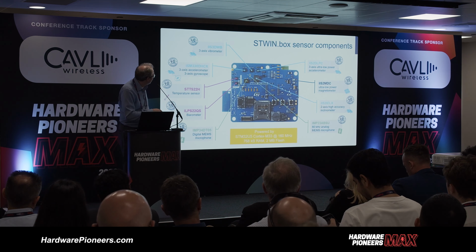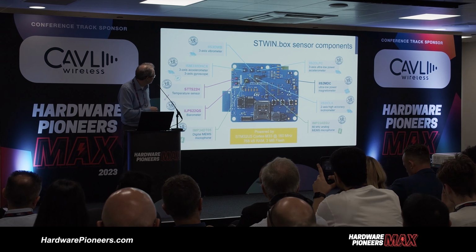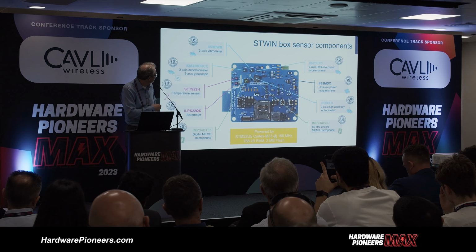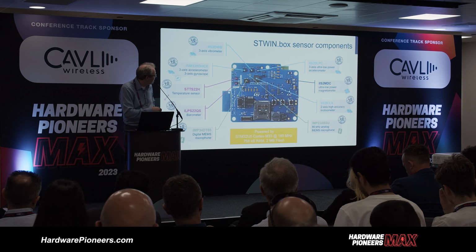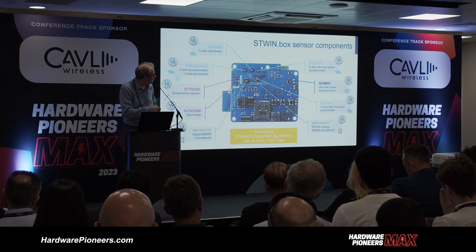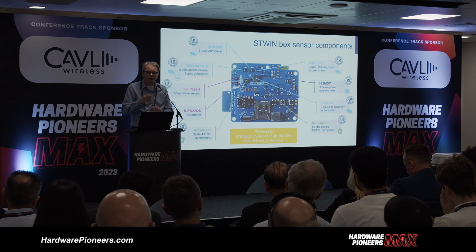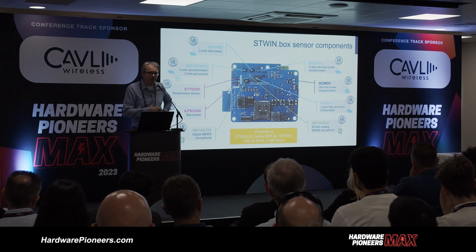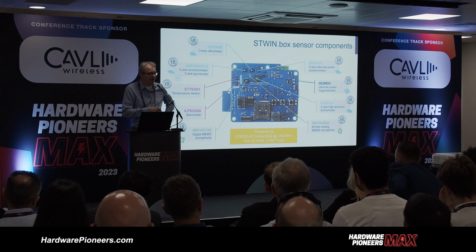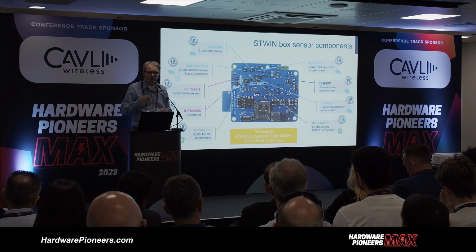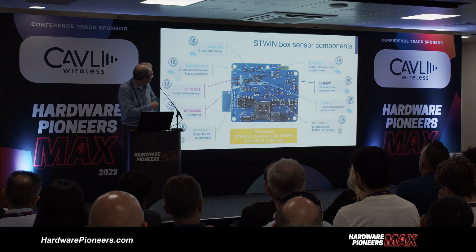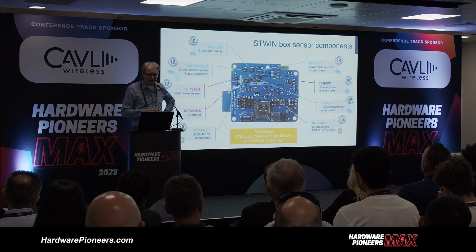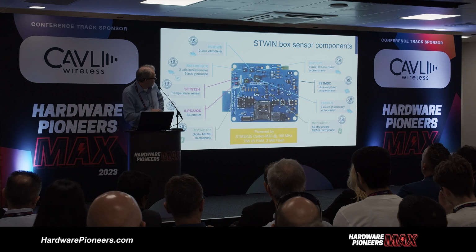We can start from here, the acceleration sensors. So to mention that we had the 6 kilohertz component. This was the 6-axis IMU, but we have also one which is a very low power component. This could be used, for example, for the initial wake up of the system, that this component takes only 0.4 microamps of current, and then it could wake up the whole system based on a small shock on your device. And it's actually being used very commonly together with this other guy, which takes more current when it's making the measurements. Also, we had here the inclinometer component for the accurate angle measurements.